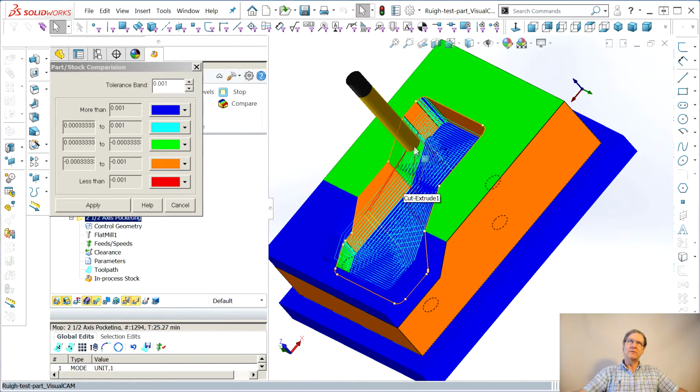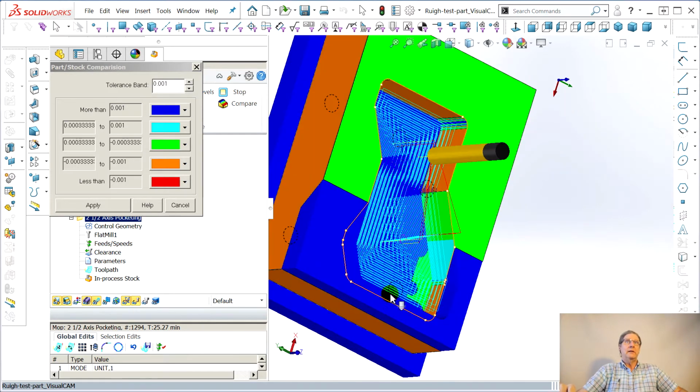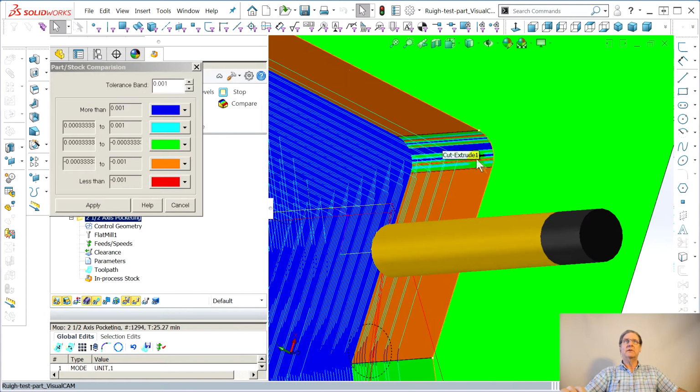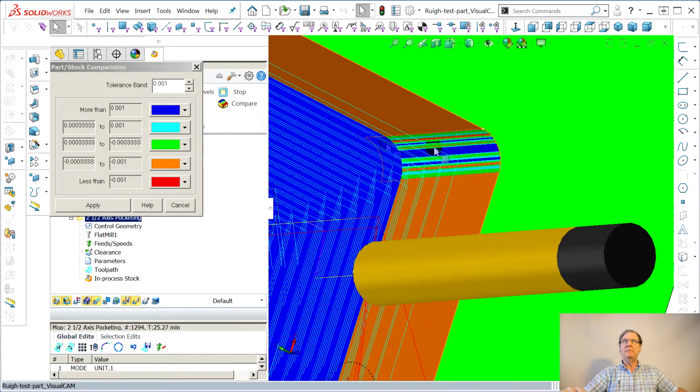As it is, some surfaces it gets perfect, near perfect, right? Once again, is this some deficiency where they can't do the math? They're doing integers and they get this rounding error that causes a problem? Or is it being more truthful? And these corners, look at this rainbow of colors. Blue, that means right in the corner here where G-code can do a perfect arc. Can't do an ellipse, it has to make segments for that. But G-code can do an arc. A machine can do an arc. Why is this all rainbowed?